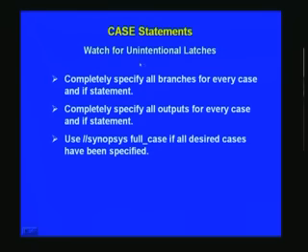And you have to be very watchful, otherwise you will be creating unintentional latches as such, which we have already considered. Therefore, do not do this: completely specify all branches for every case, at every case statement, for every possibility. You have to consider it wholly. So also for if-else-if statements, you have to consider all the possibilities, do not leave anything to chance. Otherwise you will get into trouble later on.